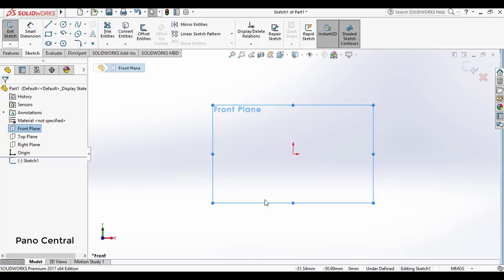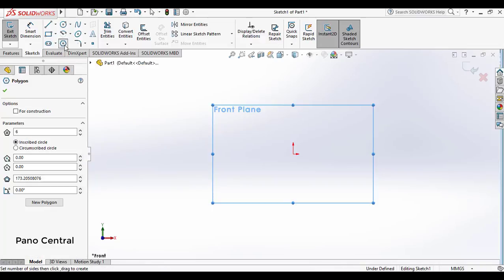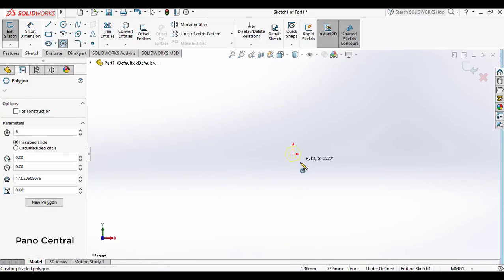So I'll be using like 7.6 or 7.7 millimeters for the size instead of exactly 8 millimeters, because I'm making it for a 3D printed part that I've already printed. Because of the shrinkage, I have to make a custom Allen key. That's why I'm making it. If you want to make any size, you can make it. So we'll start by making a polygon, and we will start by clicking on the origin.